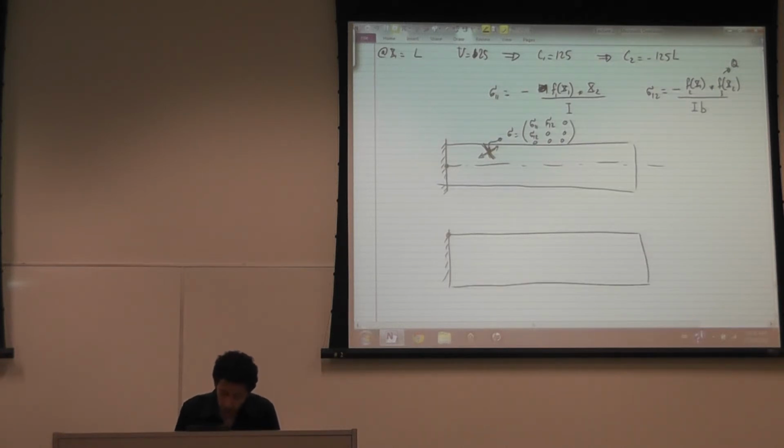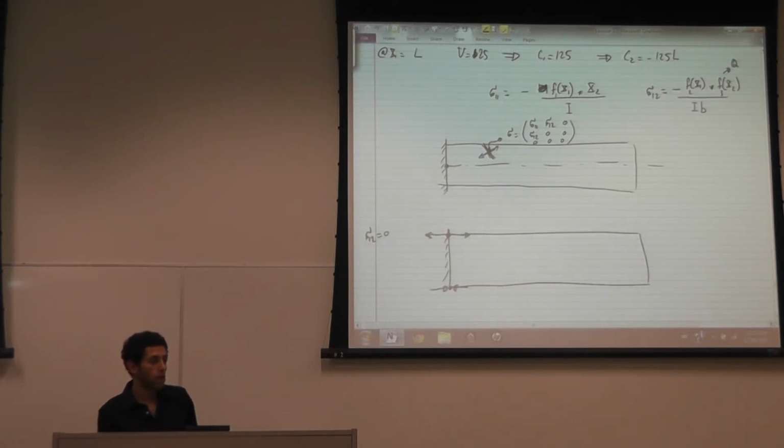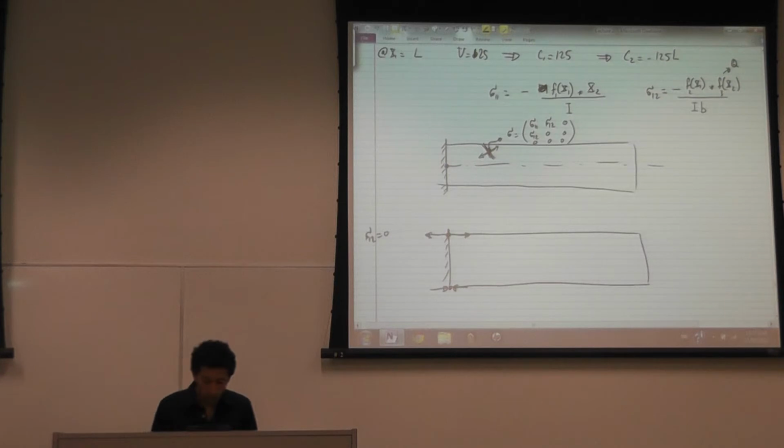right here, sigma on 2 is 0 at the top. And so your stress matrix has only sigma on 1. And so your principal stresses are in this direction. Tension and 0 in the other direction. At the bottom, we've got compression and 0 in the other direction. So this is the direction of your principal stresses.